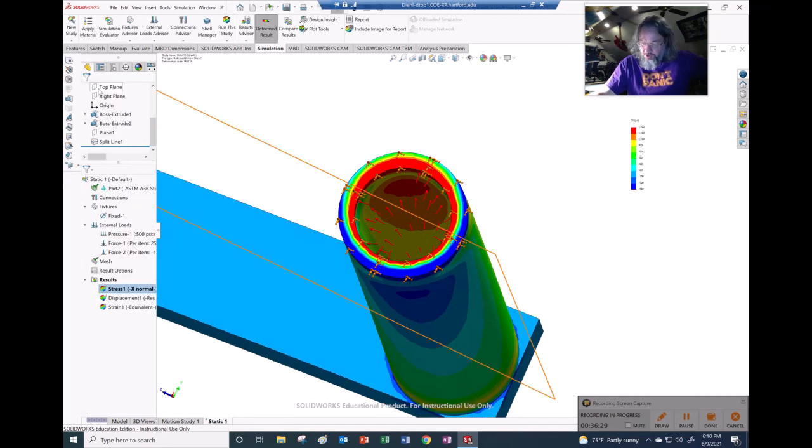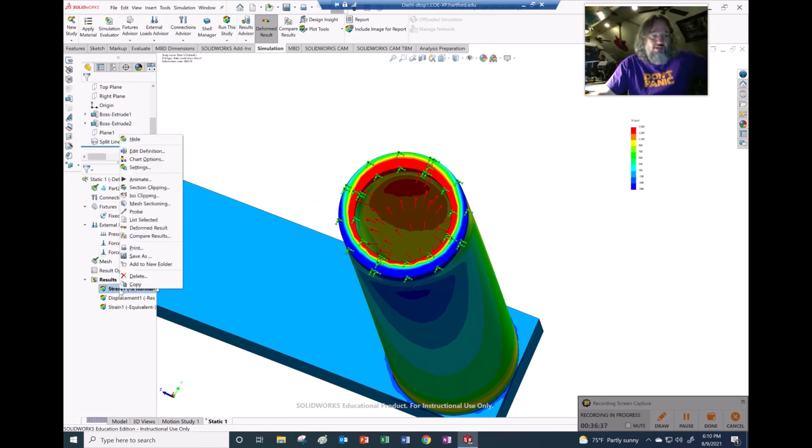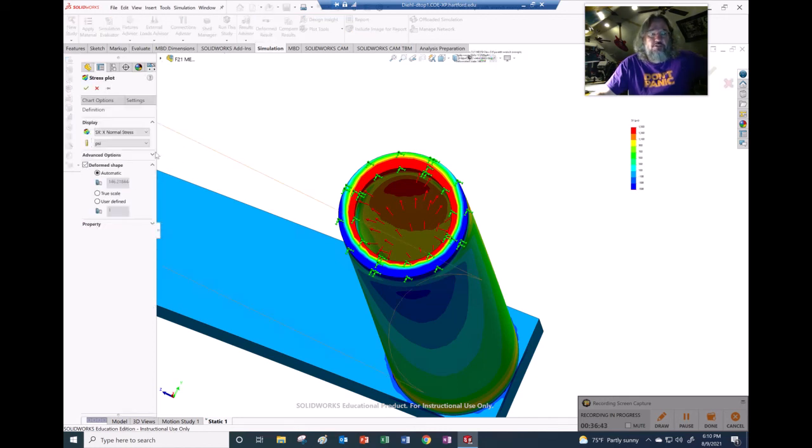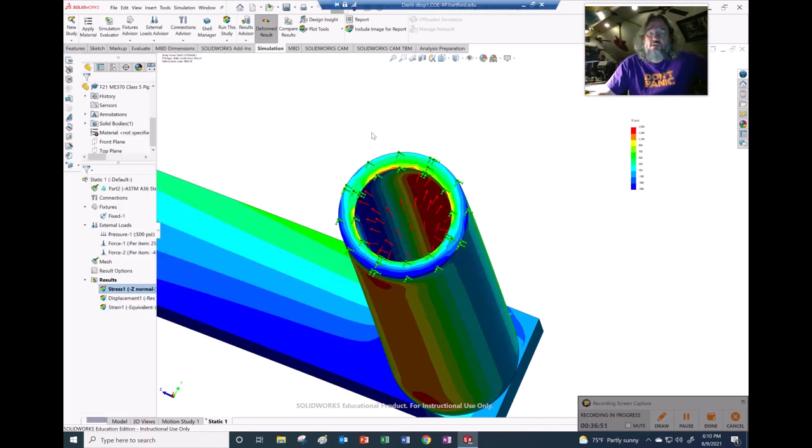We could actually attempt to look at the hoop. We could see what the hoop says we're going to be. That would be in the stresses in the z direction in this one. So I'm going to edit my definition and go to the z direction. And that's the last one I'll do as part of this. And maybe we'll investigate this in another time, in another way.